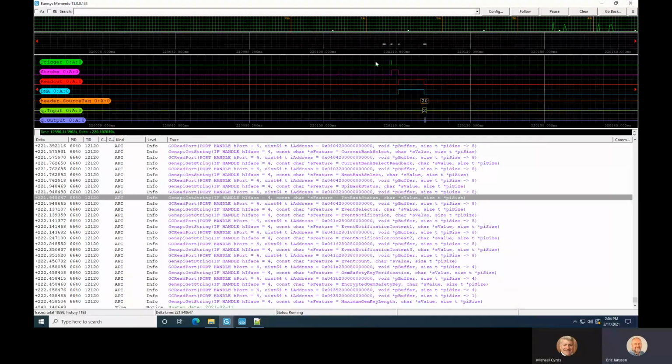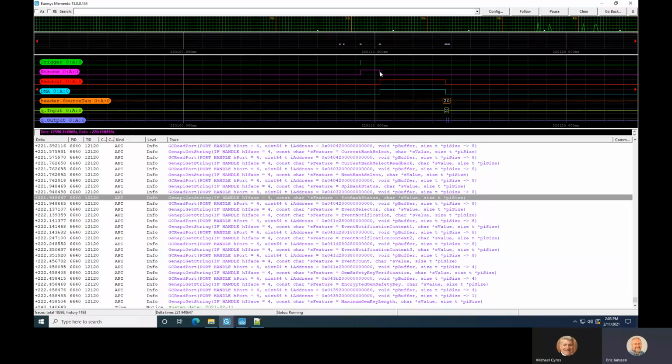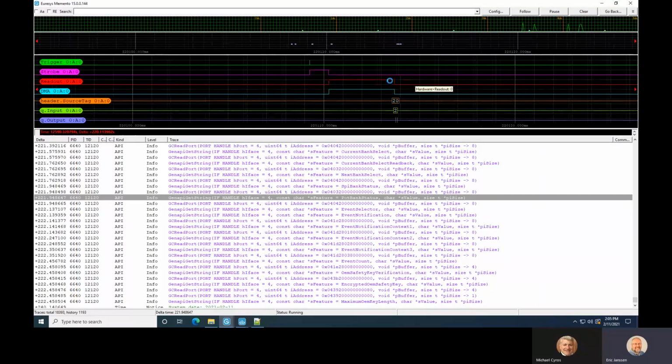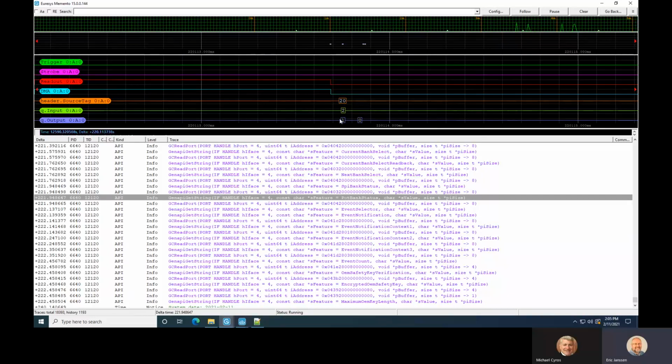Okay, I'm zooming in. And here I have my trigger. So this is when the trigger is sent to the camera. Here I have my strobe, which also covers the exposure time. So during this time, the camera gathers some light, and this depends on the setting of the camera. Then during this time, the camera transfers the image to the frame grabber. And after this, the frame grabber provides this image to the application. So once the output pool receives one buffer, it's when the application receives this image and when the application finishes this image. So how can we measure timing?